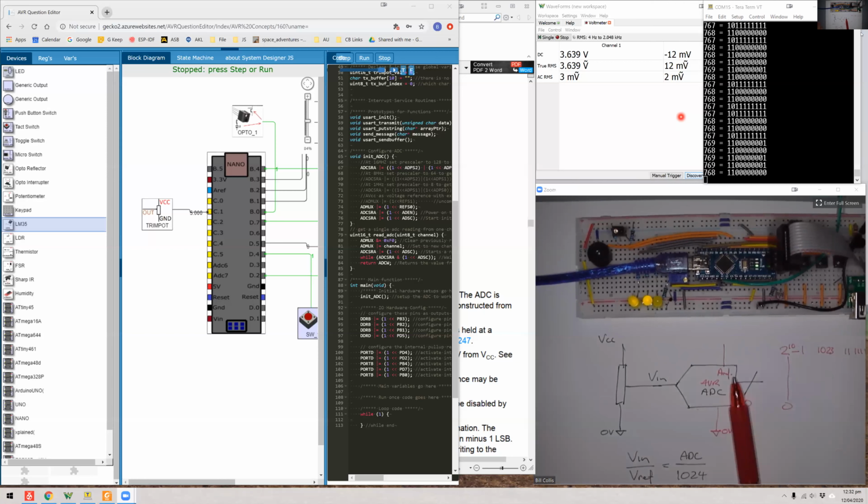And now, first of all, we'll have a look at this schematic just to show you what's happening here. We'll look in the simulator. We can adjust this from 0 up to a nominal 5 volts, which is VCC, just to show you what's happening here. And we've got 6 input channels, C0 to C5. These, as well as being analog, can be binary or digital inputs and outputs. ADC 6 and 7 can also be analog inputs, but they cannot be binary inputs or outputs. So they're only available to use as ADC values.